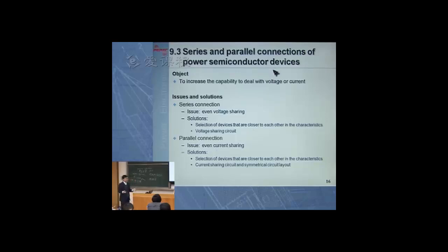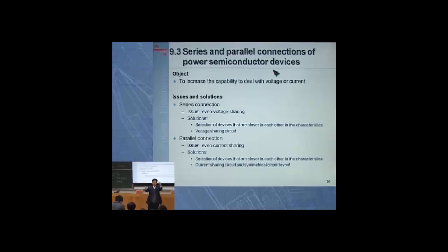Parallel and series connection of power devices. This is very useful when a single device cannot deal with large current or high voltage. When you need to deal with higher voltage, you connect several devices in series. When you need to deal with large current, you connect several devices in parallel.